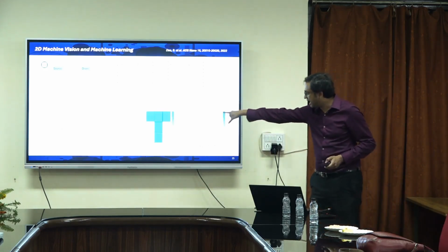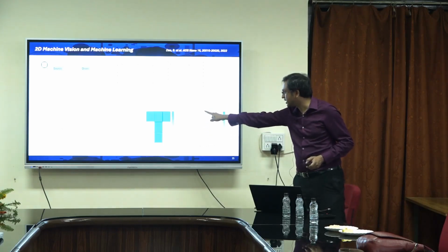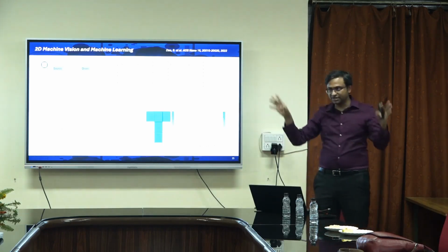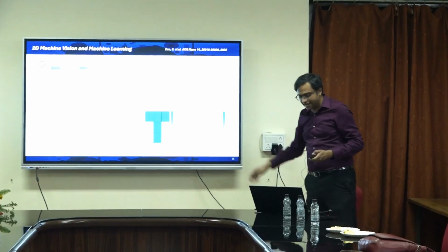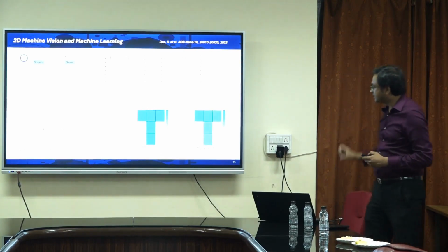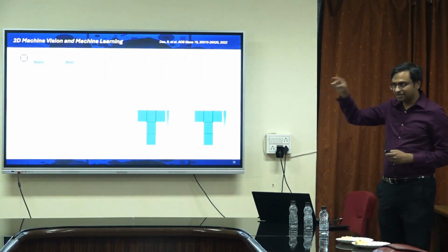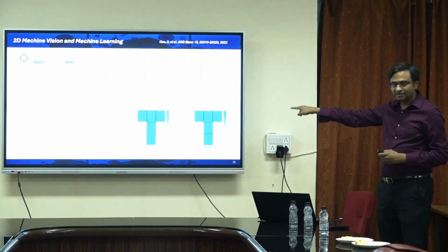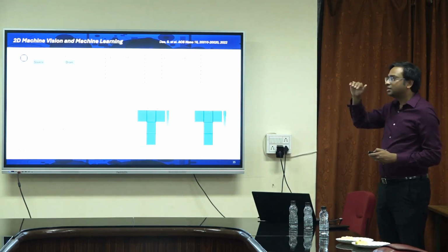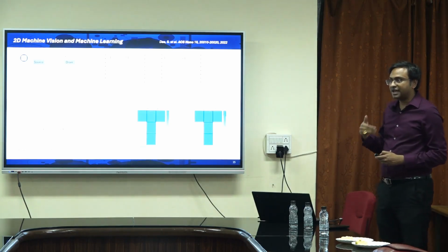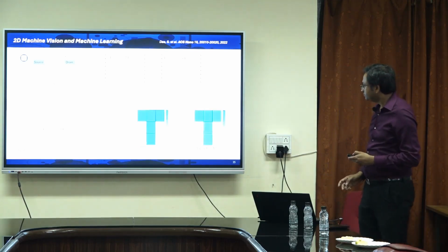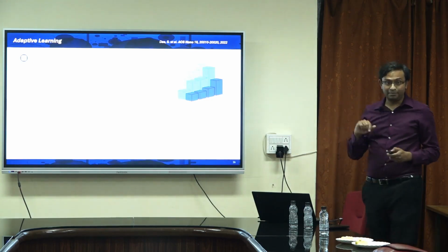So this is light information. You can see the LED intensities, right? 0 and 20. 20 is the highest. So this is a letter T that I'm showing through the array of my devices. You saw that array that we have built. Let's see whether it can, if the video runs. Yeah. So as I keep shining the light, you see the conductance of this device array also now replicates the information it has seen, right? And then it remembers. So it is almost like my memory that forms, that I see T, I remember it's the letter T. Okay. The next thing is, it is very adaptive, right?